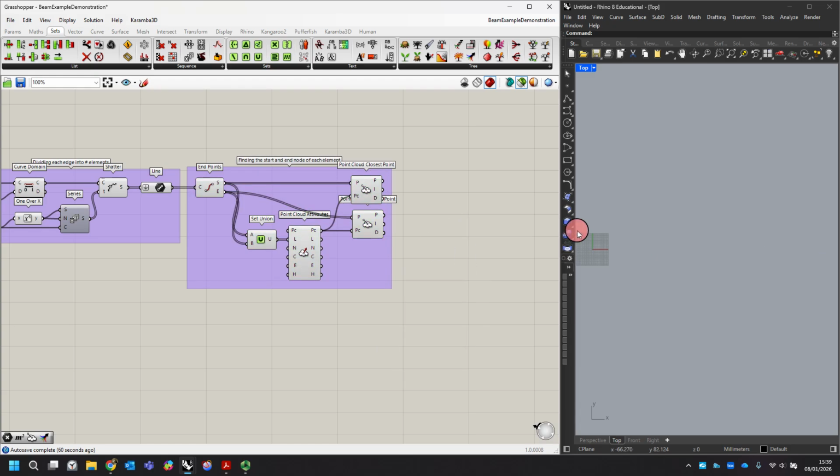Okay, so we're almost done in terms of defining the mesh. Obviously, we've got a little bit more to go afterwards, but the final step is going to be to show that we can generate a set of unique nodes and a unique set of elements that we're going to visualize in Rhino, just to check in a second.